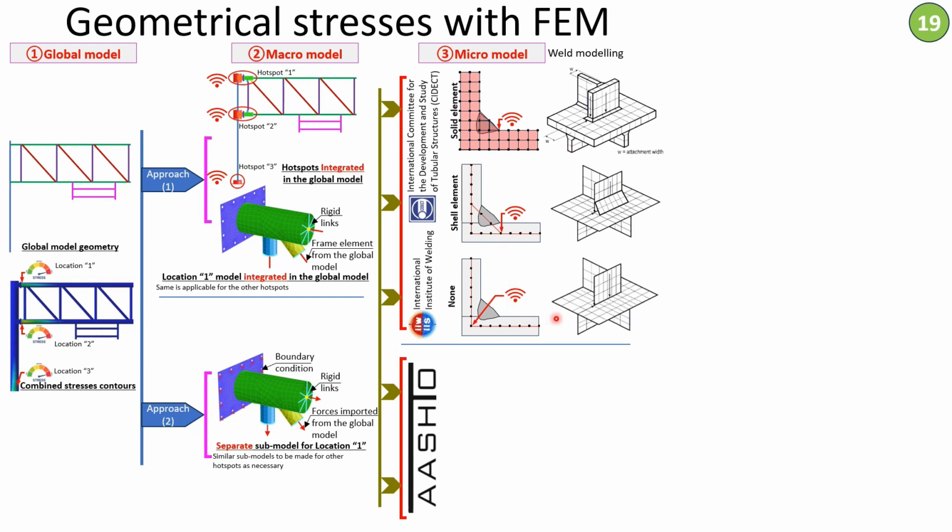Means that you're not modeling the weld itself, and you believe that rigid connection between the welded plates is enough to represent the weld, and in that case your hot spot is at the intersection of the connected plates. Now let's move to the American school.